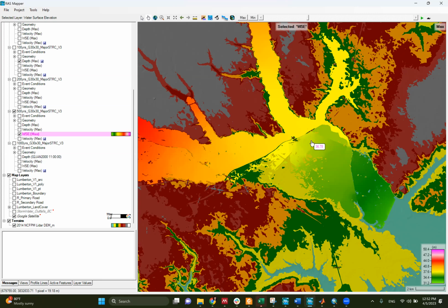Yeah, I believe the water surface elevation is in meters, that all the maps that I sent you are in meters. But I'm not sure, somehow some of you, when you got these maps into HEC-RAS or in GIS, found it is in feet, like it has hundreds. So right now, can you see the number here? It's like 36. If you multiply it by 3, it will give you around this number, which means that this number is in meters, but this number is in feet. So double check, okay?